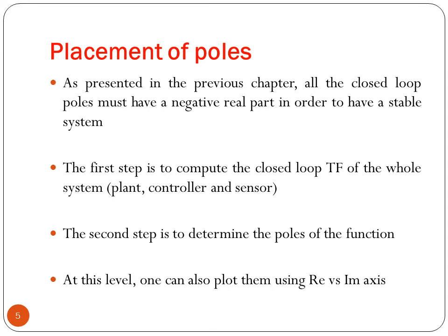The graphical way: when inserting the poles in the xy graph, the real versus imaginary graph, we can see if we have at least one of the poles with a positive real part, the system will be unstable. And the second method is an analytical method. We will focus only on the real parts of the poles, and make sure that all have a negative value.